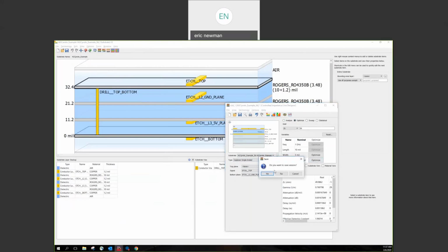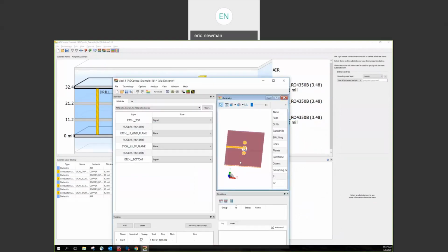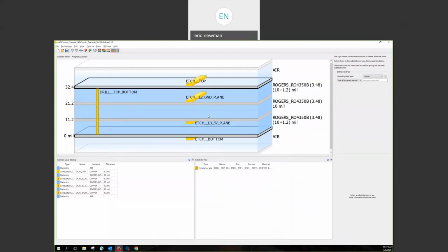So yeah, you have access to these tools, this controlled impedance line designer, and it's all part of our interconnect toolbox. This VIA designer is also part of that. So it allows you to get both those transmission lines and the vias designed appropriately for your system. You can go in and add different layers, different kind of feeds, coaxial feeds, microstrip feeds in this case. You can do differential vias and run simulations and get models for your vias to use in your top level schematic simulation in ADS. Anyways, we'll close that out and save more details for that for another day.